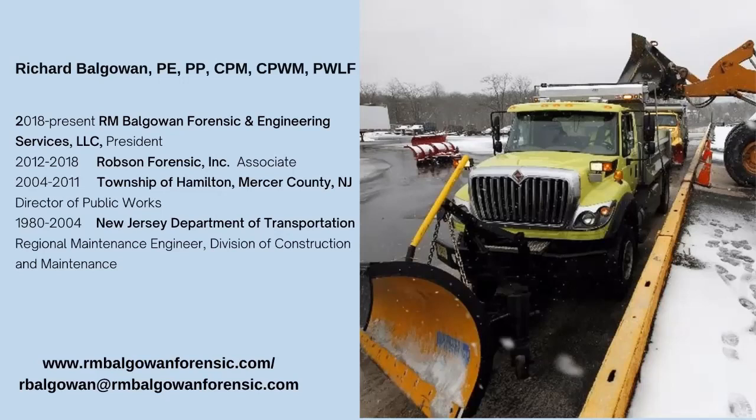Another thing I did when I was director of public works in Hamilton Township, we set up a snow and ice management system, which was part of our asset management system. Every snow fighting piece of equipment in the town had a pavement temperature sensor in it, and sensors that would let us know how much salt that truck was putting down per lane mile, how much liquid, if it was pre-wetting the salt with calcium chloride, or if it was applying a liquid salt as a pre-treatment to the roadways.